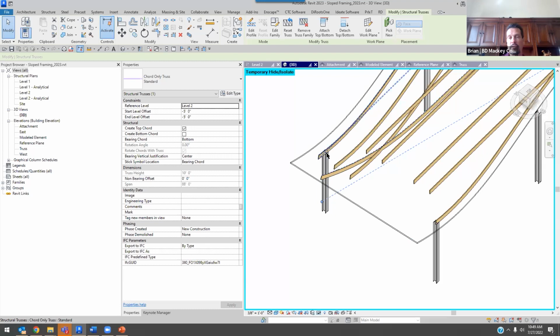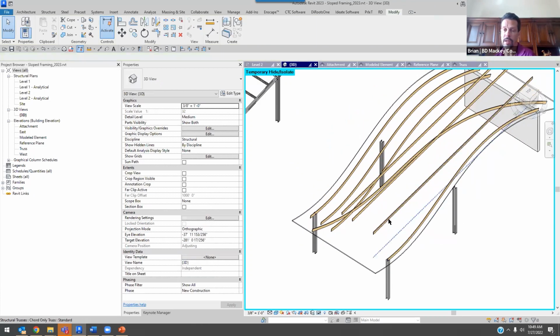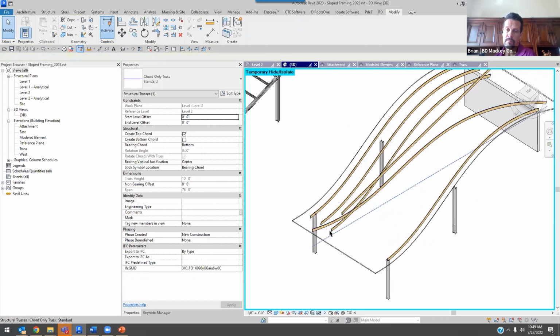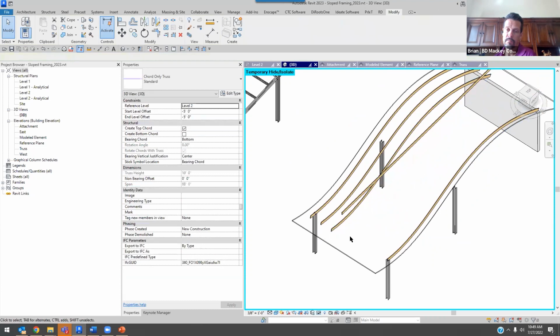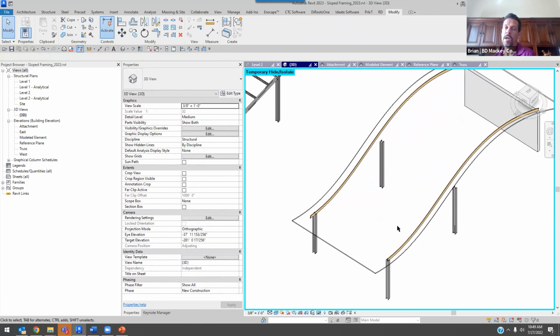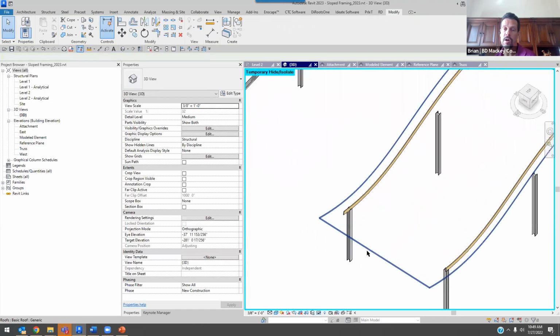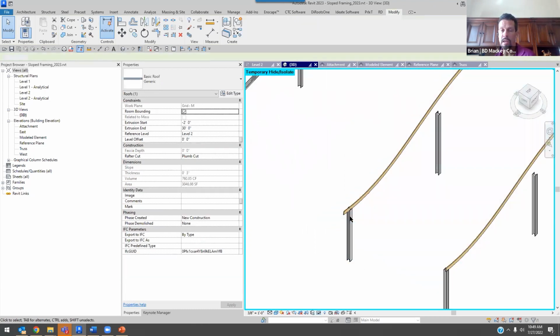So the downside to doing trusses is you can't use them in a beam system. Advantage of doing trusses on something like this is you can go through and set this up and start getting it to work. Now I'm going to actually delete all these intermediate ones. That's my crazy truss. There's this one. Now, one of the advantages of doing this, and something that's really, really cool on this, is I'm going to draw a beam across the endpoints of this.